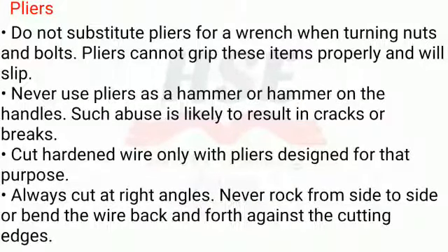Pliers. Do not substitute pliers for a wrench when turning nuts and bolts. Pliers cannot grip these items properly and will slip. Never use pliers as a hammer or hammer on the handles. Such abuse is likely to result in cracks or breaks. Cut hardened wire only with pliers designed for that purpose. Always cut at right angles. Never rock from side to side or bend the wire back and forth against the cutting edges.